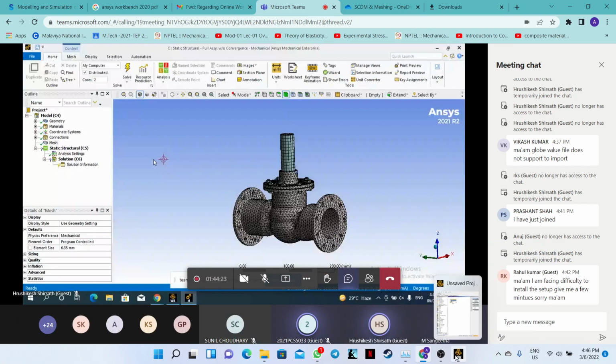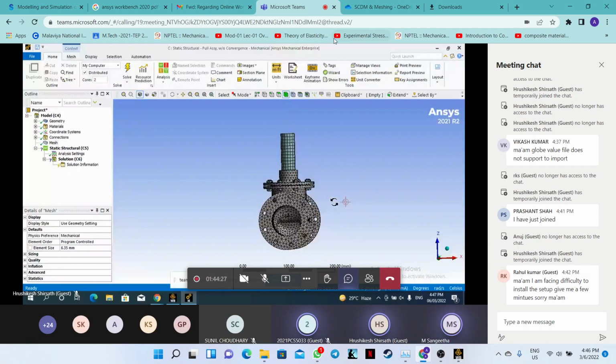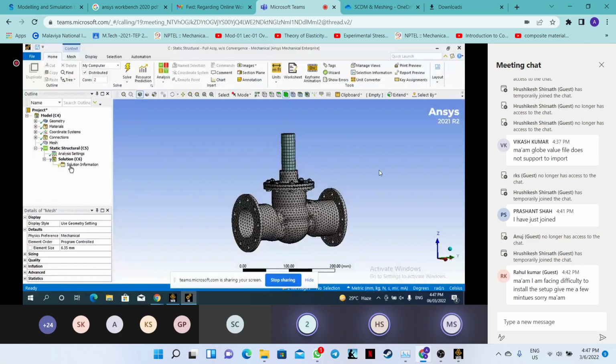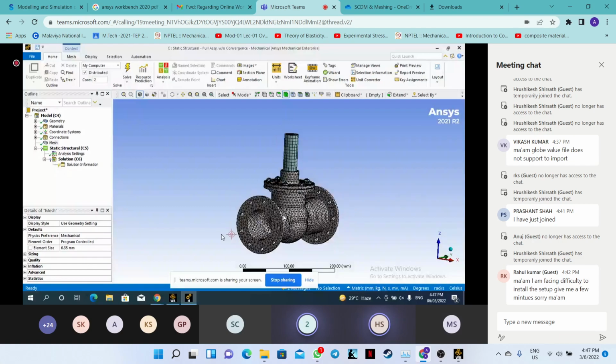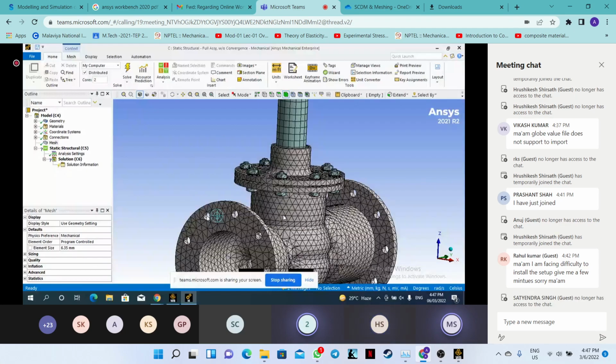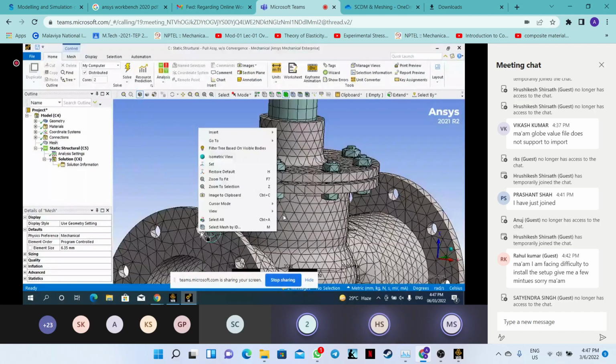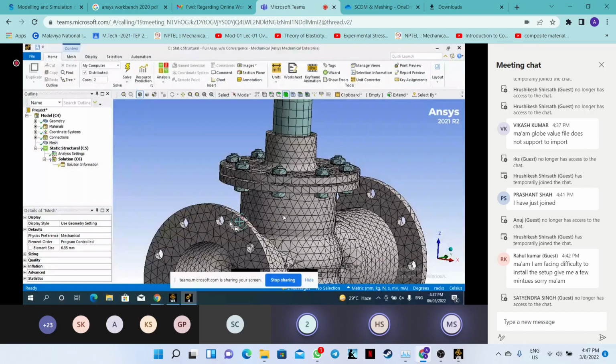So please do the name selection procedure, how we have to do it. Please see how to work with the name selection. Yeah, select one of the whole surface. You can zoom in. You have the right mouse button there. Wherever you want to zoom in, you go to that region and drag with the right side of your mouse button. Yeah, select the whole surface. You are currently in body selection, okay? So go with the surface selection.